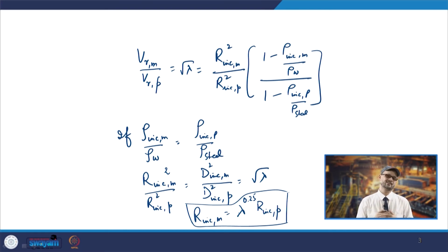If you take its square root once it will be close to 0.55, and taking another time, something close to 0.76. So, for a 1/3 scale model, the inclusion size in the model should be about 0.76 times the diameter of the inclusion in the steel.